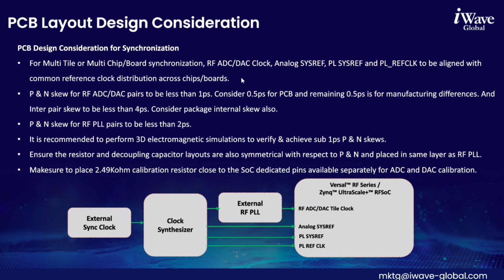To do that, we have to generate all the clocks from a common synthesizer so that they are all synchronized with a single clock. And when we use multi-board synchronization, we need an external sync clock running across the multiple chips or multiple boards, and it has to be synchronized.